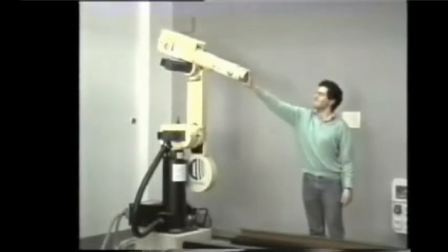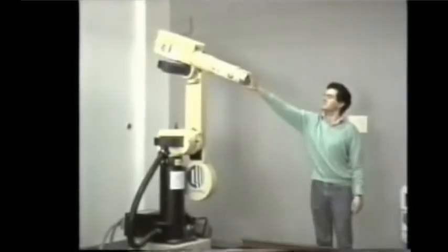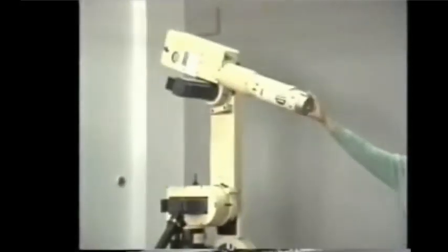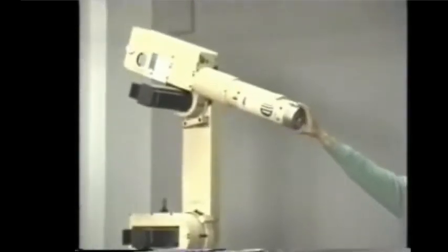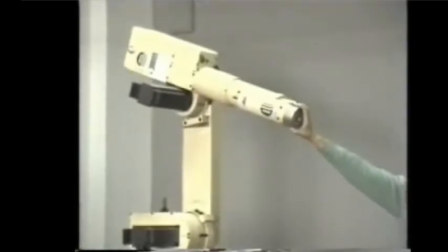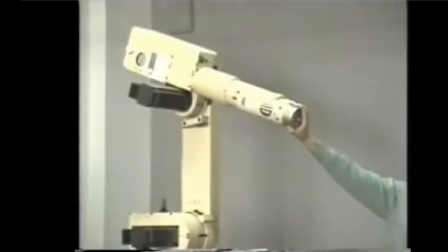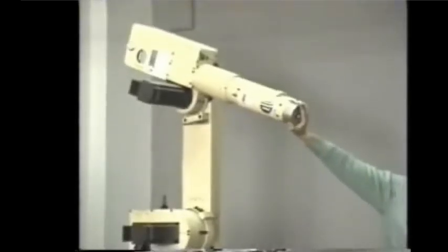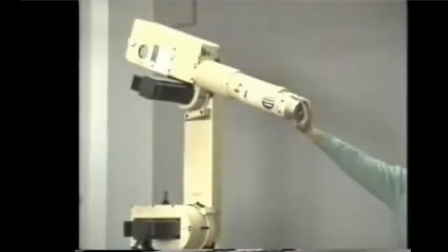In this case, we can choose proportional gains at the Cartesian level, and we can have a stiff control, with large proportional gains. So if we push, the robot will not move. And we can push in any direction if we have selected large stiffness gains in the various directions.